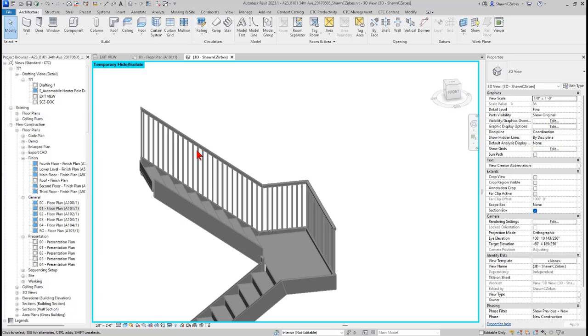If you're in AutoCAD and you want a very specific preview of something that is AutoCAD centric, maybe you're doing Civil 3D and you want to show a better representation of an actual tag, maybe an alignment tag. You can do the drawing, have the alignment tag in the plan, and take a screenshot of it from AutoCAD. Make your background white though when you do it. It's going to look better in Nexus. But take a screenshot of that and save that screenshot someplace.